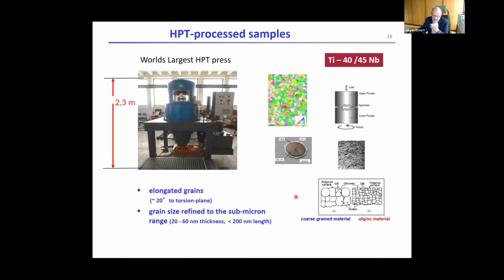One specialty that we have in-house is the so-called high-pressure torsion. Like I said, you have two anvils, a little disc button shape sample in between. You apply the pressure. You have a torsion deformation. You get very fine grain sizes. And this was something that we tried for small scale implants, not for big hip replacement parts or something like that, but for relatively small scale parts.